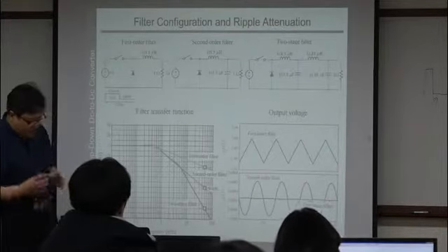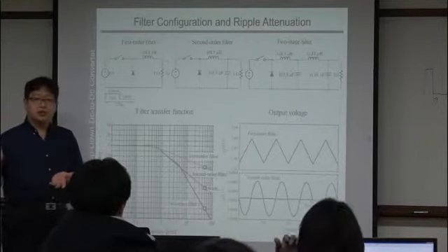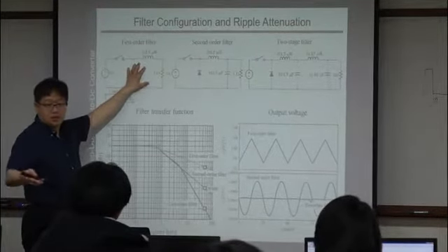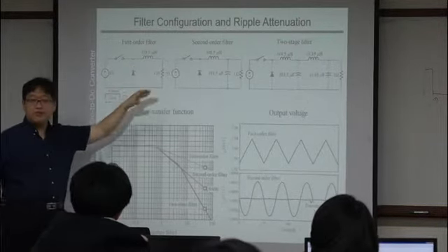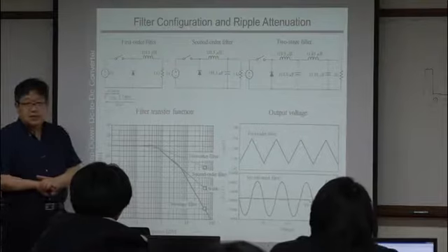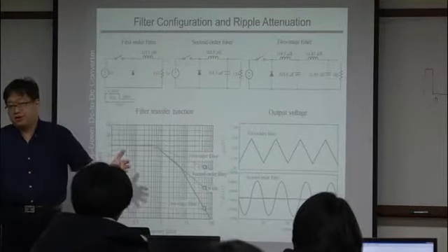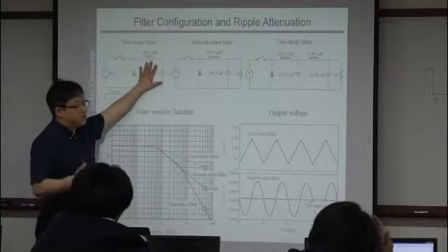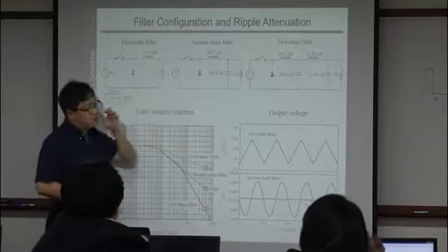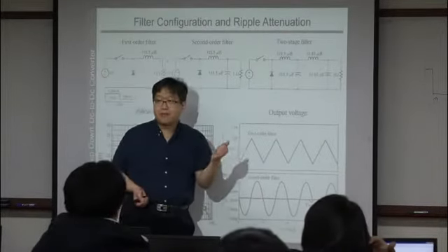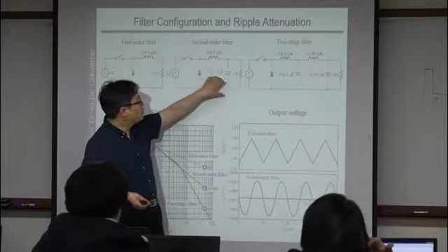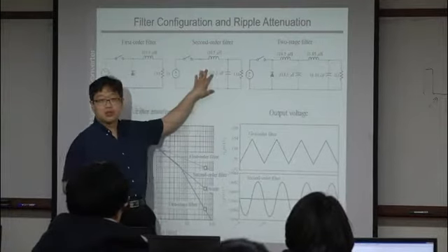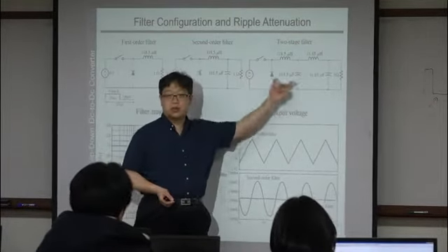So, for example, the battery charger. In that case, you can apply this because your battery voltage is what? That is not controlled, right? Well, in fact it is controlled, but in many cases, your battery itself is already a very big capacitor. Battery itself is a very big capacitor. So, in a battery charger, you don't use this kind of strategy. Then what about the power supply? For power supply applications, you can go with this or this. But this circuit is much, much preferred compared to this because of the number of components.